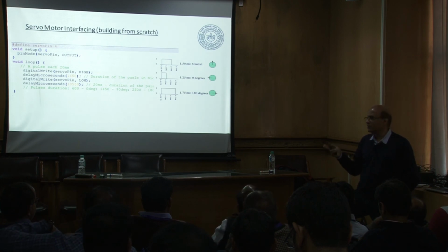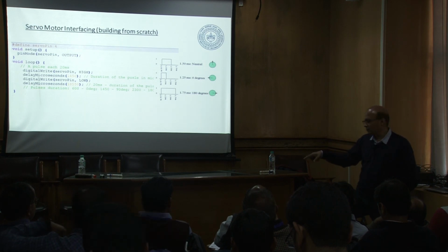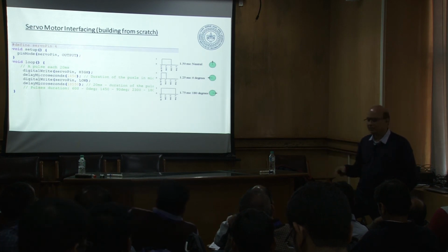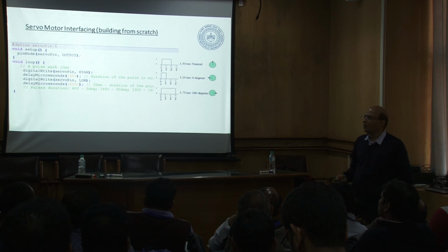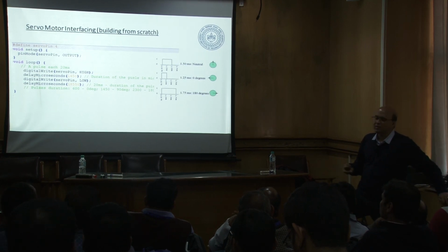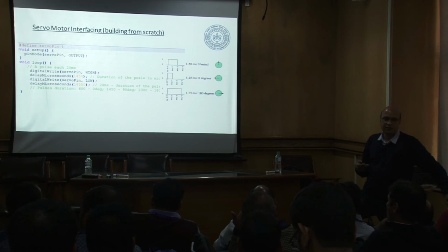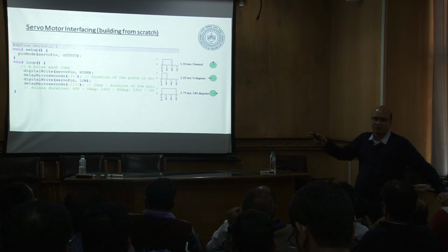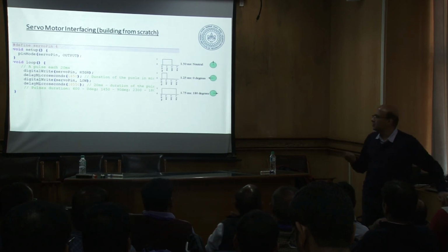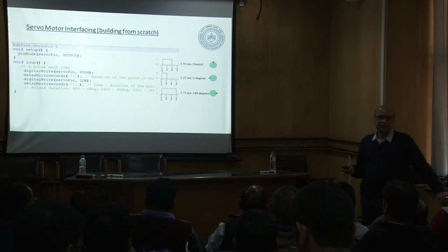You want to interface vision with one of these robots. So first you see an object, then you can do segmentation, take out the CG of that object, then you can do the inverse kinematics and go there and catch it. Okay. So as you're looking at the experiments, also think about what you plan to do. So on Sunday we'll have this project session, Sunday is fully devoted to this only. What do you want to do? Okay. So those of you who are very familiar, you can take a higher level thing like vision-based integrated control. Okay, and those of you who are just starting, you can take something simple like sensor interfacing, control of tooling systems. Okay, is that okay?